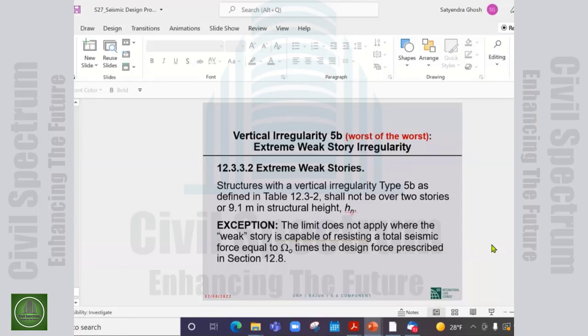So look at that part of the NBC serviceability load combinations, which we do not have in our codes, and go with that. But again, I would say that in the vast majority of cases it doesn't make any difference, because gravity does not cause drift, unless, again, this is a big unless, it's a very unsymmetric building. Then gravity will play a role.